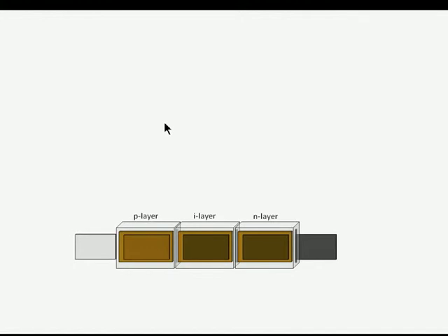The typical amorphous silicon thin film solar panel manufacturing line is a vacuum chamber of 3 separate compartments. In this configuration, the panel enters the first deposition equipment with already pre-deposited transparent conductive oxide, a process which is not illustrated on this slide. On the left side is the first chamber compartment, which is used to deposit the so-called P amorphous silicon layer.